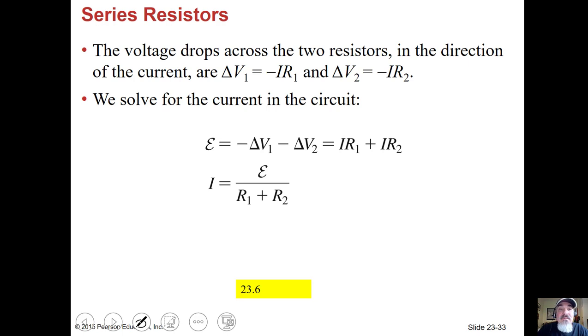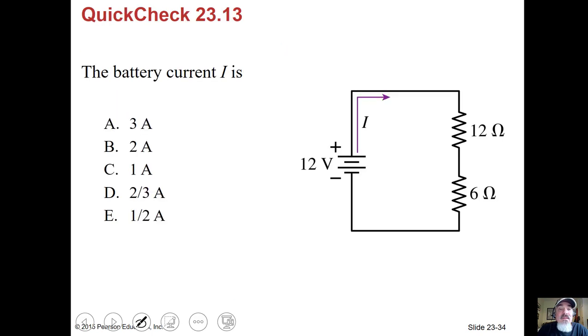Okay, so in this example, you know the current is the voltage divided by the resistance if you put everything together. So let's see, how much is the current in the battery? We've got 12 volts to work with. From what you saw on the previous slide, maybe I can call this one R1, V1, this could be V2 and R2.